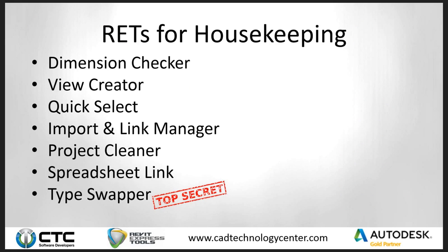All right, so today we'll be utilizing a handful of the free and paid tools from both Manager Suite and Project Suite to do a little cleanup in a Revit file. These tools will be the View Creator, Quick Select, the Dimension Checker, Import and Link Manager, Project Cleaner, Spreadsheet Link, and also a beta preview of Type Swapper. It's a not yet released tool. It's currently going through some beta testing, so we'll give you a sneak peek at that.